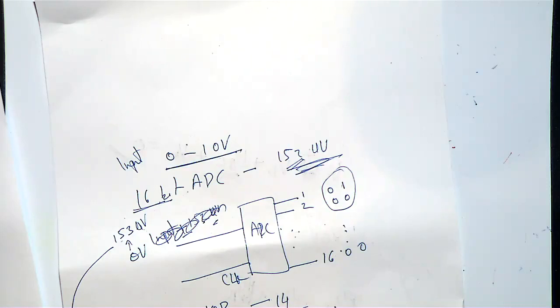I don't know where the 0.5 comes from; it's a calculation. To be honest, I think about 13 pins were stable. The remaining pins were just jumping. Then you can improve the design, and get up to the effective number of bits. So your calculation should be based on effective number of bits.